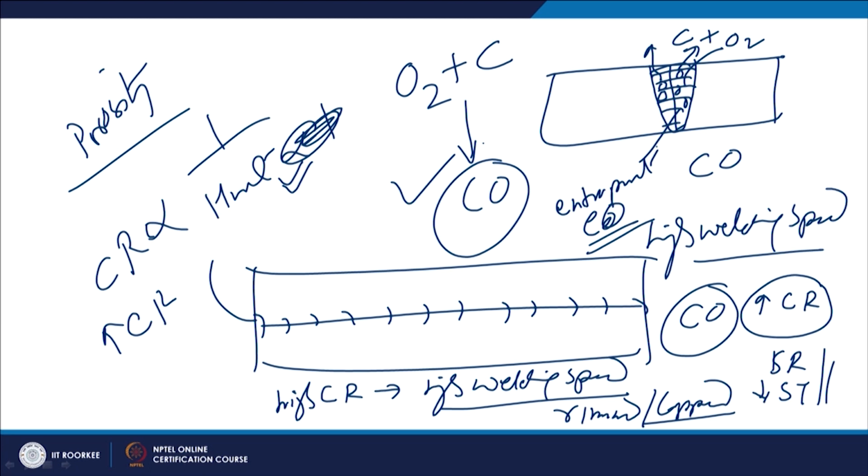In general, this is a commonly encountered problem in the autogenous welding of low carbon steels, or the rimmed or capped type of low carbon steels, because in autogenous welding we simply supply heat from an external source for facilitating the fusion of the faying surfaces, so whatever oxygen is present in the base metal or in the molten metal reacts with the carbon to form carbon monoxide.